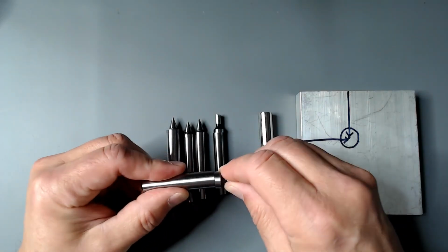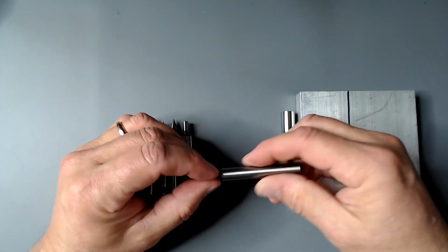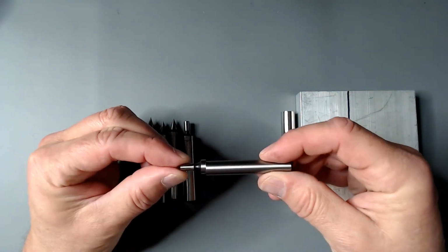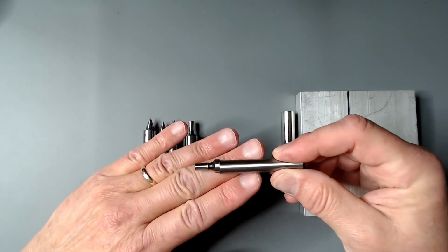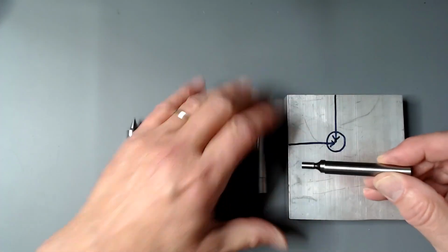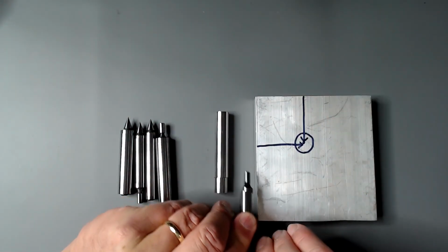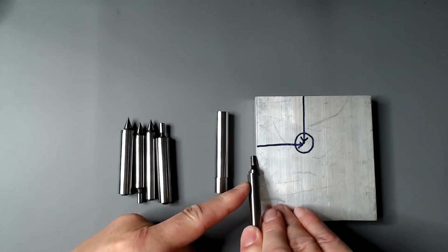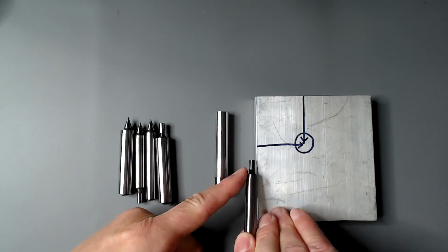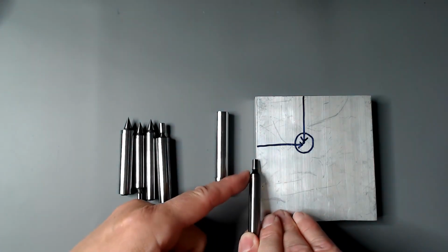As this thing is rotating, and this will make more sense when we get out at the machine and I show you how to use it, it'll start out off center, like so. Then, as you approach the workpiece, as we're coming into it, and I'll have this at an angle here so you can see what I'm talking about. As we come in, and this is rotating, eventually this will line up perfectly and it'll run perfectly true.